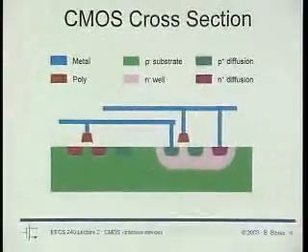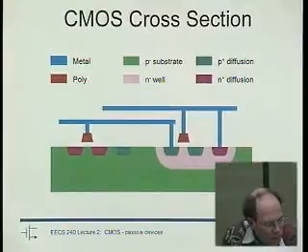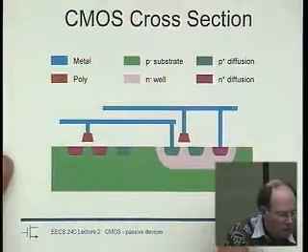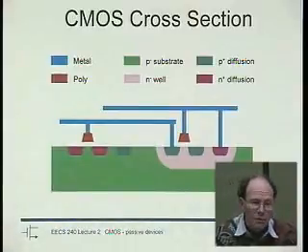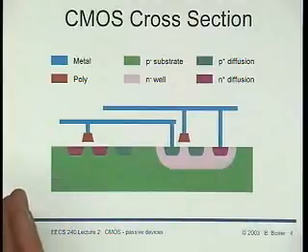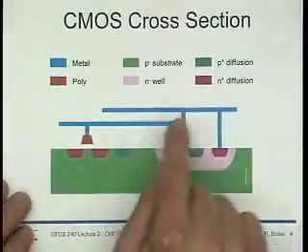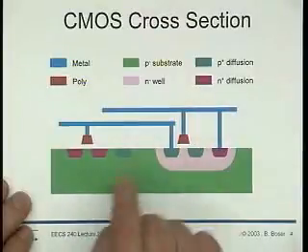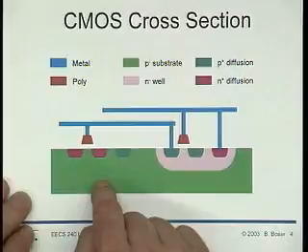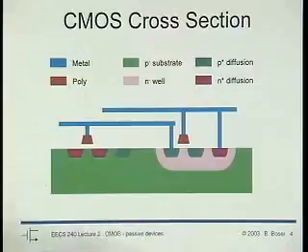I said that we wanted to look at cross-section. So here is a very simple, not to scale and so on, cross-section of a CMOS process. So first here at the bottom, this green stuff is the substrate. The substrate could be N-type or could be P-type. Today, most of the time, it's P-type. So that means that you immediately can make an NMOS transistor here. And the NMOS transistor then uses N plus diffusion in the P substrate. Right? Then invariably we get diodes here, right?